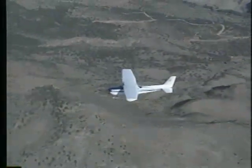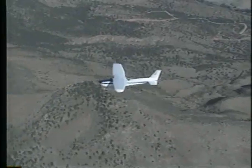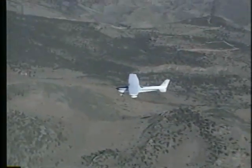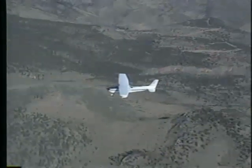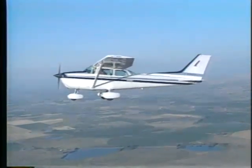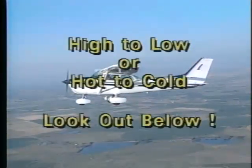Obviously, this could be dangerous if you're flying over obstacles or high-rising terrain. It could also place you far off your appropriate VFR cruising altitude. A helpful memory aid to assist you in determining whether you're higher or lower than before is the phrase, "When flying from high to low or hot to cold, look out below." This means that in these situations, you're going to be below the altitude indicated on your altimeter.